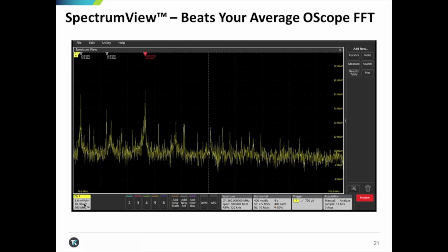For EMI applications, it provides automated peak markers as well as an ability to apply windowing to filter out undesirable frequencies or harmonics. The underlying IQ data that's used to create the spectrums shown by Spectrum View can also be used to calculate RF versus time waveforms, which show how various characteristics of the RF waveform vary over the entire acquisition, not just where spectrum time is positioned.